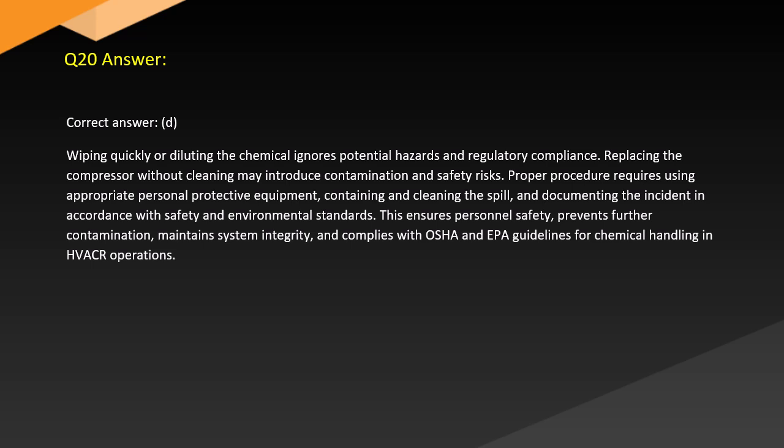Answer. Correct answer. D. Wiping quickly or diluting the chemical ignores potential hazards and regulatory compliance. Replacing the compressor without cleaning may introduce contamination and safety risks. Proper procedure requires using appropriate personal protective equipment, containing and cleaning the spill, and documenting the incident in accordance with safety and environmental standards. This ensures personnel safety, prevents further contamination, maintains system integrity, and complies with OSHA and EPA guidelines for chemical handling in HVACR operations.